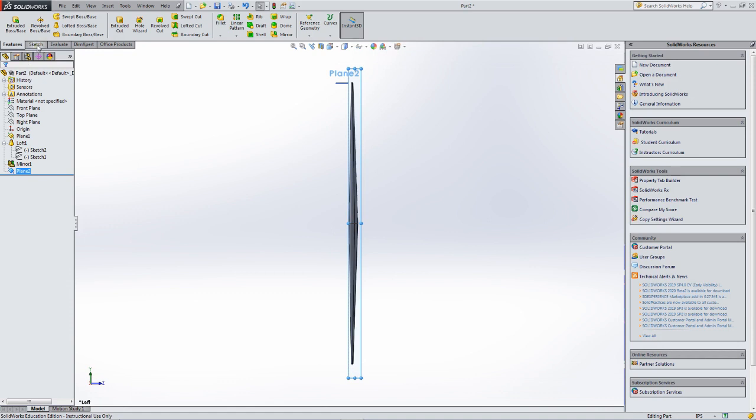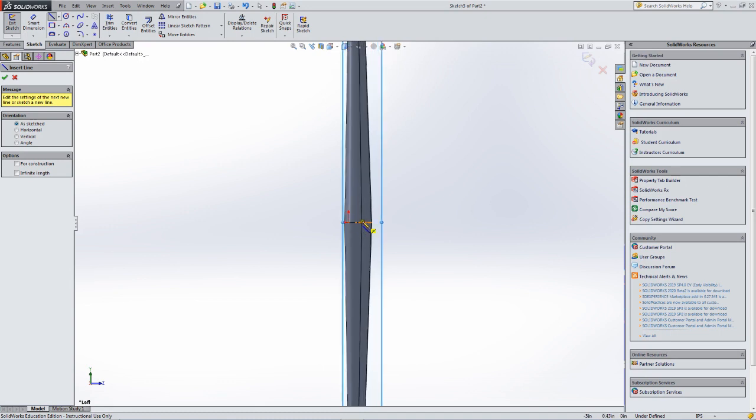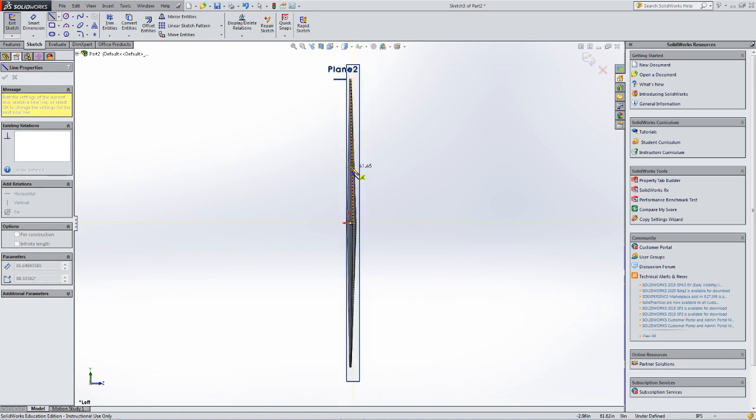It's not going to be an F-16 fuselage cross section. It's going to be more of a stealthy airplane cross section. Stealthy airplanes tend to have kind of slab sides. And I want it to intersect the wing right about in the middle of the wing here. So I zoomed in, I'm on that plane, I'm going out here. Fuselages tend to be 10 feet wide, something like that.